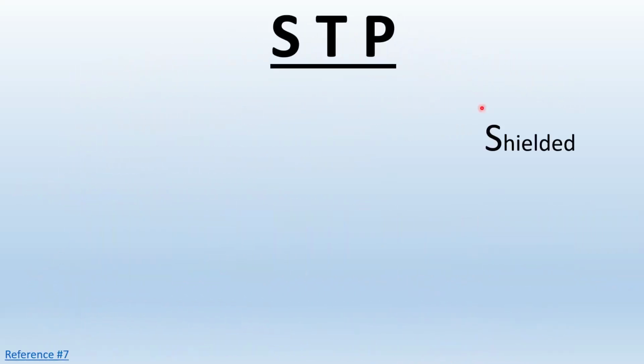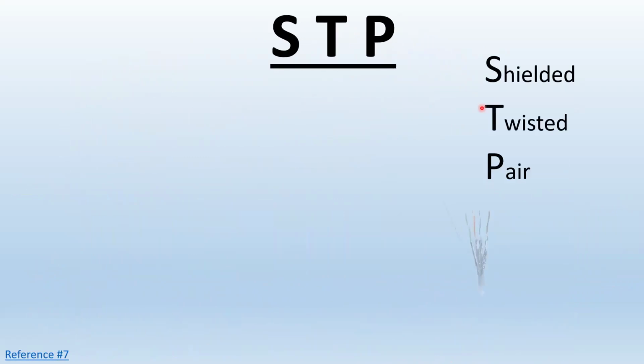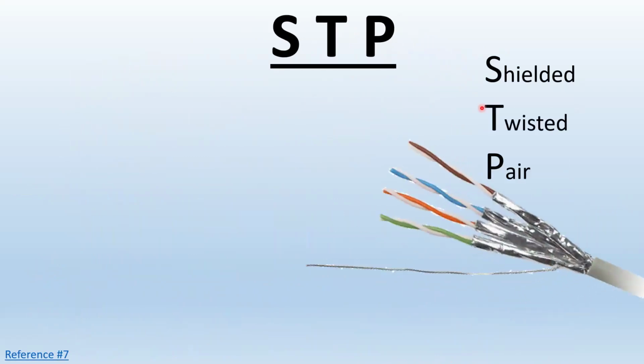Shielded twisted pair. That's what it looks like, more or less. You have tin foil surrounding every pair, in some cases. And then you have the grounding cable, the grounding conductor that basically runs along. It's bare wire. The grounding cable or the conductor has to be connected as per instructions. So sometimes you want to connect that in one end only, sometimes you want to connect the other end only, and sometimes you need to connect that at both ends, usually at both ends.